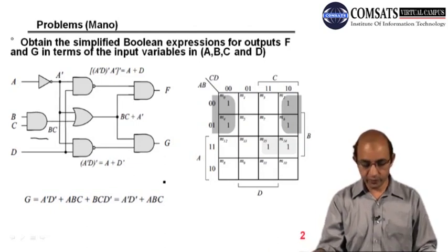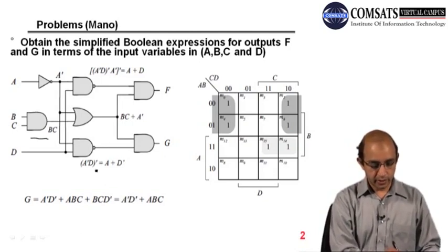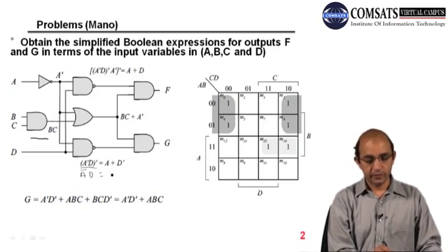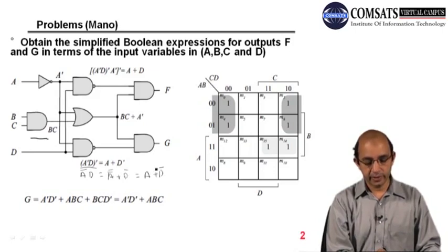If I have to solve this, what I can do is A complement and then D, and then I have to mark the whole complement. So what we normally do, we break the line and change the signs. So A double complement plus D complement. This double complement will cancel, so we are left with A D bar. So this is A D bar.